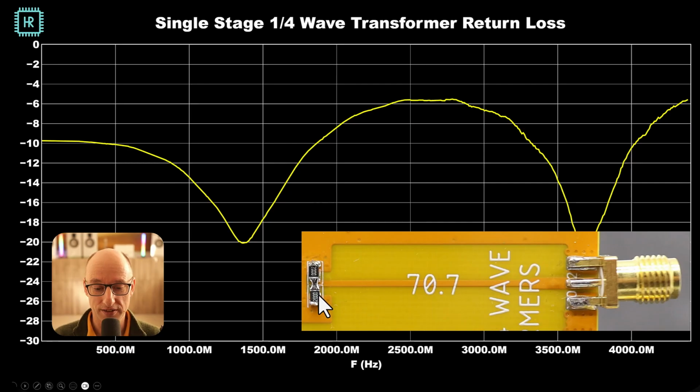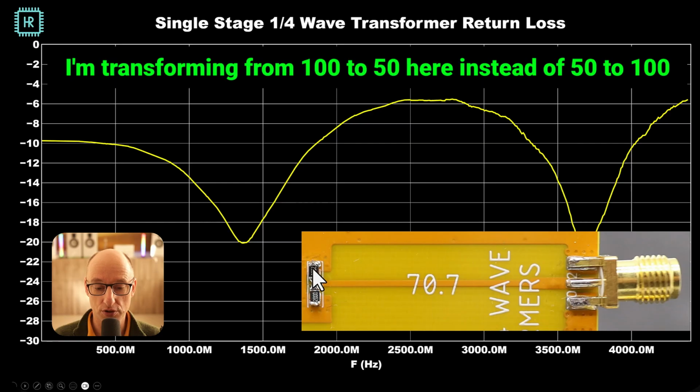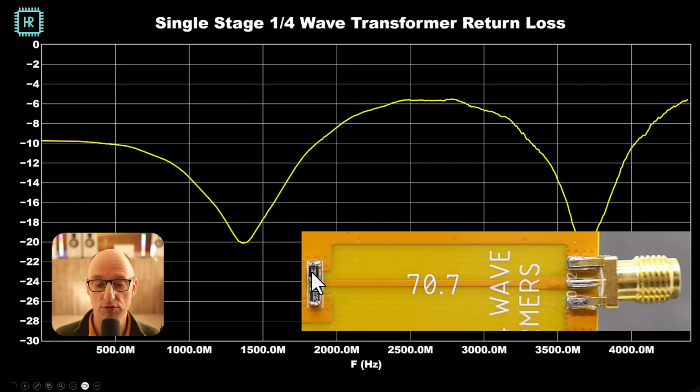So what I did here is I made a board and I have two 200 ohm resistors. So in parallel, they make 100. The reason I did this is because, yeah, these components have inductance. If I make 2 of them, then the inductance will be less. And you see a lot of vias around here because I also don't want to add extra via inductance. So if you put a lot of them in parallel, you have less inductance. This line here is 70.7 ohms and it converts into a 50 ohm line and then an SMA connector. Later in the video, I'll show you how you can calculate the width of these lines.